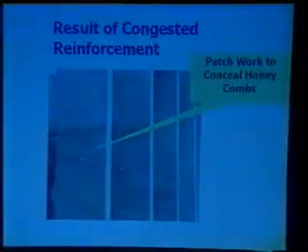Now, gentlemen, this is a very commonly observed sight. This is the underside of an RCC overhead water tank. You have poor concrete, reinforcement exposed. This is a very commonly observed condition. Now, you see this patchwork, and all this is to conceal the honeycombs.